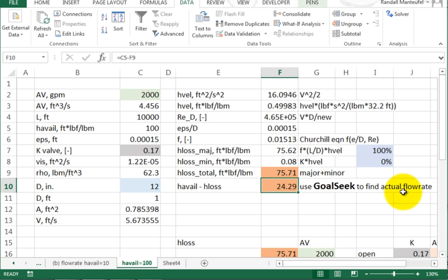If you look, the inner diameter and the nominal diameter are very close to each other, but they're not spot on. Because our flow rate was given to be 2,000 GPM, I didn't try to go in and select a 12-inch nominal diameter with the inner diameter for Schedule 40, but it's listed in this appendix. If somebody has the appendix, maybe they can read it. I'll get to it right now. But it's an interesting thing to see exactly how big.